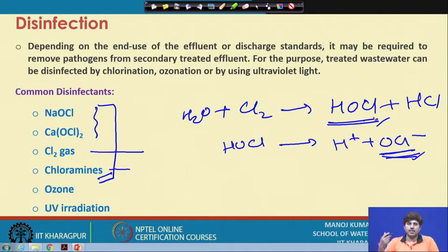the electron acceptor that can oxidize the microbial components, leading to the death or decay of the biomass or microorganisms that way. Chlorine dioxide can also be used, which is very effective, but it needs to be produced on site, which needs skilled supervision and skilled operation, and that way it is not that popular to use chlorine dioxide in the field.